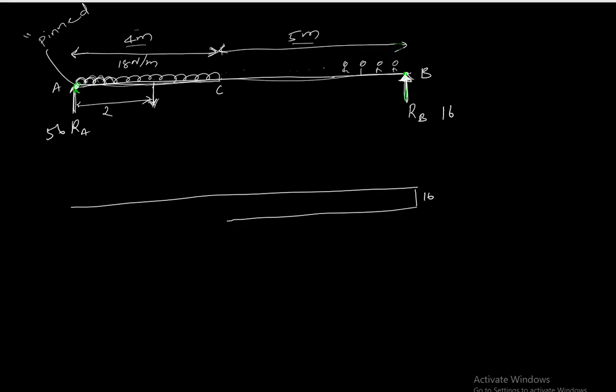Now the 70, so now you have this 18 times 4. 18 times 4 is 72. So we need to go 72 up. But if it is a point force like this, then your shear force is constant like this. But as soon as you have a uniformly distributed load, the shear force is not horizontal, but it becomes linearly increasing. So this will increase linearly up to here.